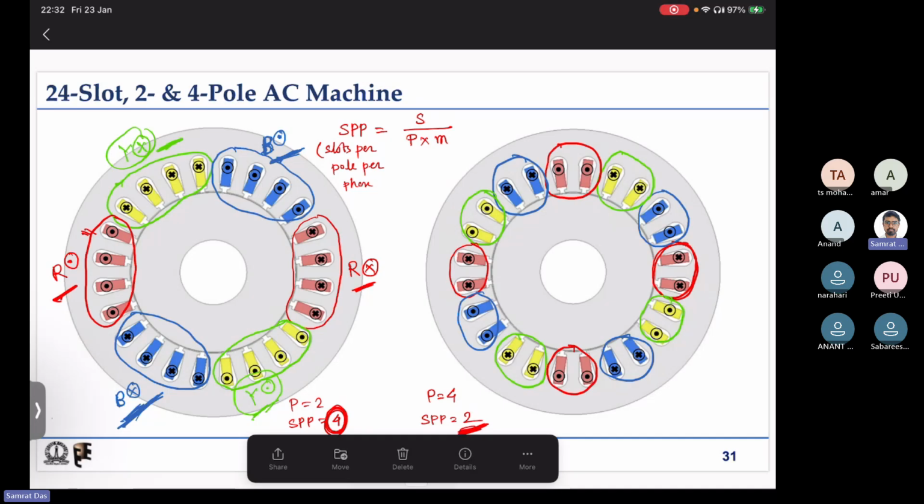If it is less than 90 degree, then depending on the angle, it will be either a six pole or an eight pole machine. If you can trace one coil, if you have the machine open, you will be able to understand.